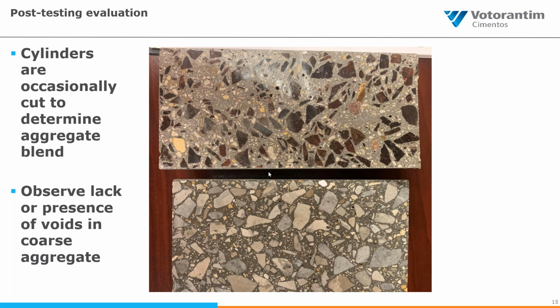As you start to get into other states, particularly southern Wisconsin, you will see a prevalence of gravel. We'd never opt to use gravel for modulus of elasticity due to bonding issues and overall weaker strength. However, we're usually pretty well off with our local limestone. They have fairly high specific gravities, decent angularity, and our gradations generally are pretty consistent, but it's something that as a producer of this type of material, we need to keep on all the time.